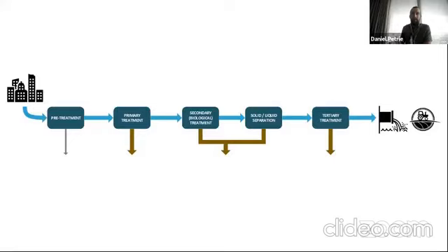Then the biomass that is grown in the biological treatment reports as secondary sludge or waste activated sludge. And then if you have tertiary treatment, you might have backwash wastewater that contains some solids as well. And then the coarse screenings and grit that you remove upfront, we just call grit and screening. So all of these need to be managed appropriately.